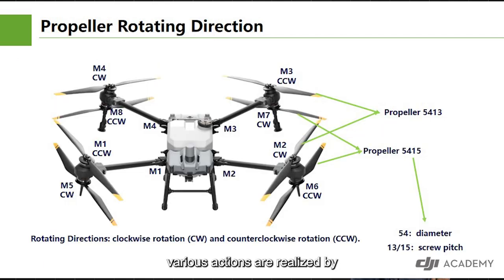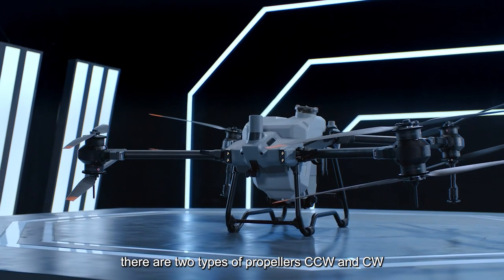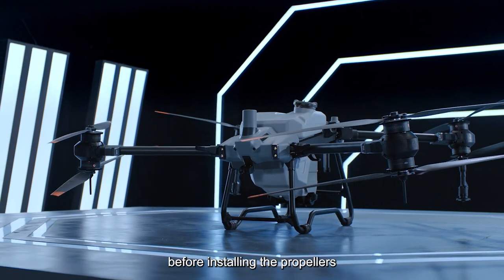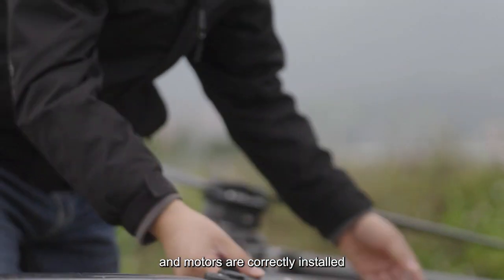Various actions are realized by changing the speed of each motor for the multi-rotor drone. For example, if the motor speed on the left is higher and the right is lower, the aircraft will fly towards the right. Generally speaking, half of the propellers of each drone rotate counterclockwise, and the other half rotate clockwise. There are 2 types of propellers, CCW and CW. Before installing the propellers, make sure that the propellers and motors are correctly matched.